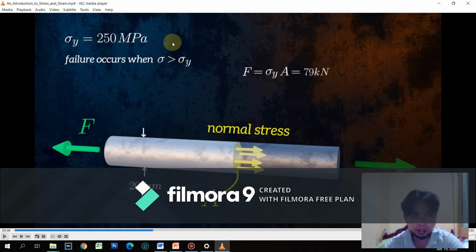So the point here is, in every material, there is an allowable sigma. When we exceed that sigma, meaning if we have an area that is insufficient, as we can see here, sigma times area, area is the determining factor. If we have a small area, the greater our stress is. And if we have a larger area, we have a greater resistance, meaning the force will be divided.